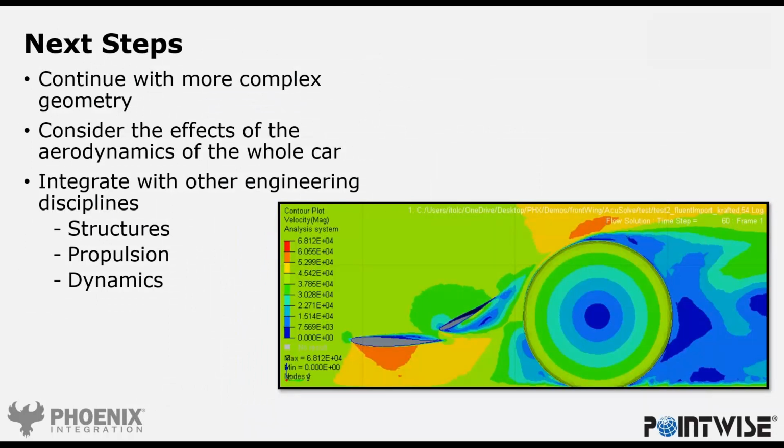So with this initial study, we can see that angles of attack that are higher at the tip give us better results. So loading the wing up at the tip where it goes around the wheel gives us better results. And for me, this makes sense intuitively. The airflow is already disrupted around the wheel, which is not aerodynamic. We need to somehow get the air over this wheel. And if we see here this cross-section, the second wing is kind of a bridge for the airflow to get over the wheel. So I think these results are correct, but it's just the beginning.